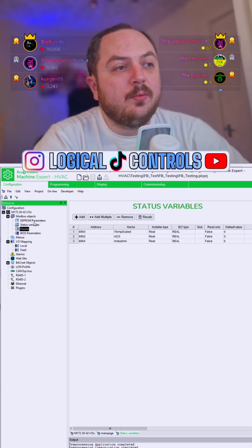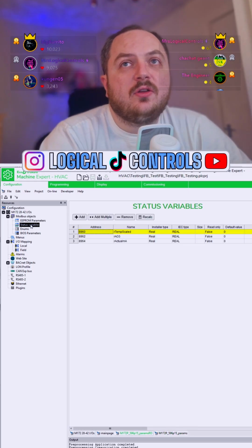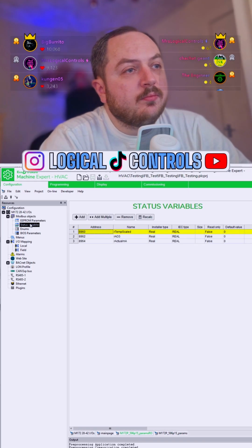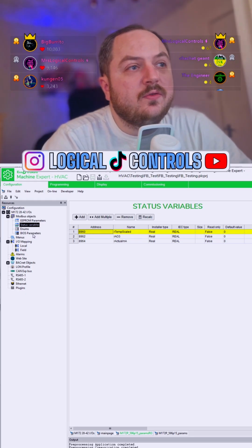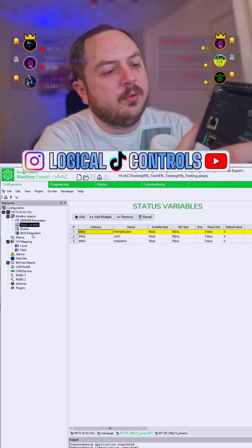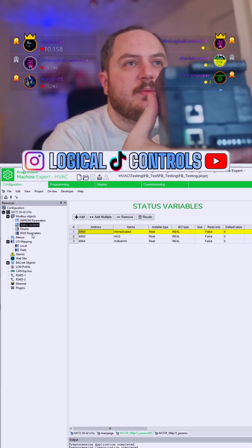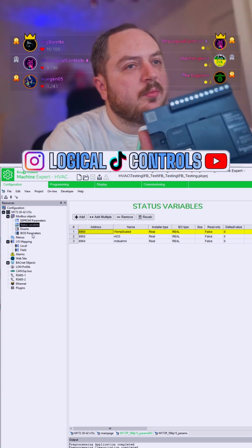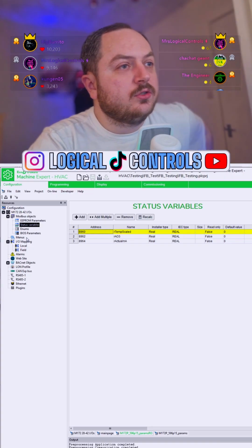You always prefer open protocols. I'm the same, David. Yeah, I do always prefer them. I just love Modbus. Modbus is great. With the TM221, you can't program with structured text. No, you're right, you can't. And to be honest, I'm with you there, John. The 241 is, for the price difference, I don't have a 241 actually. I've got a couple of 221s. I can't remember how much one of these would cost brand new, but it's not much. It's maybe like £150 or something. But for like £250 you can get the next one up, and that uses a flavour of CODESYS. It's just a better controller, a 241.